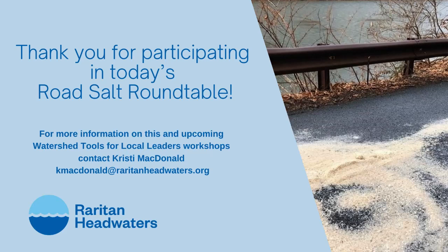My one recommendation would be, green infrastructure primarily looks at infiltration to reduce stormwater, and that's putting the stormwater into the ground. Once you put it in the ground, you're just increasing your chloride contamination. So it's reduction that you really want to look at, if you want to prevent that chloride impact.